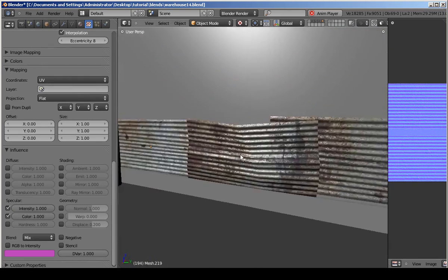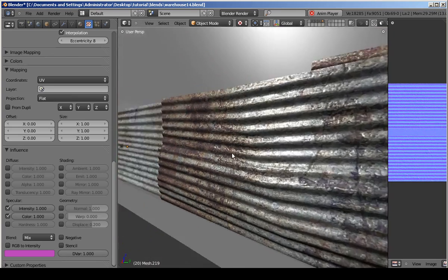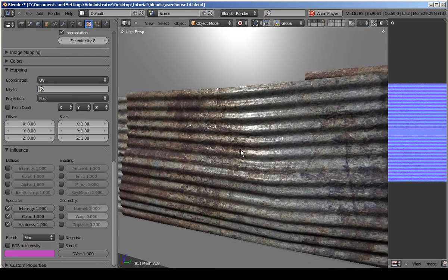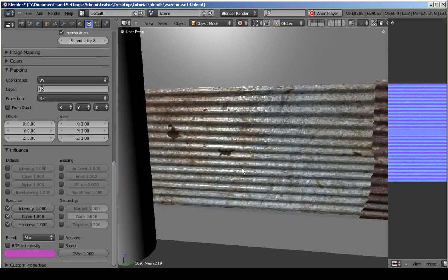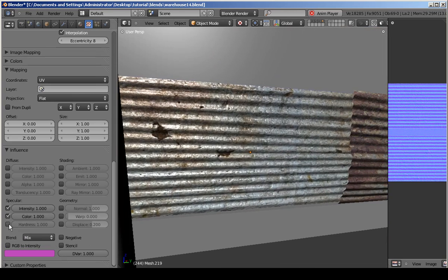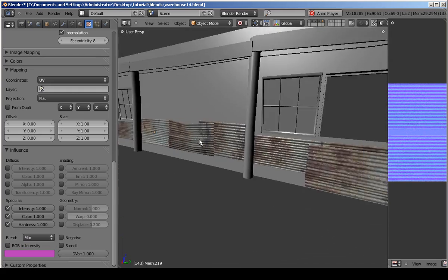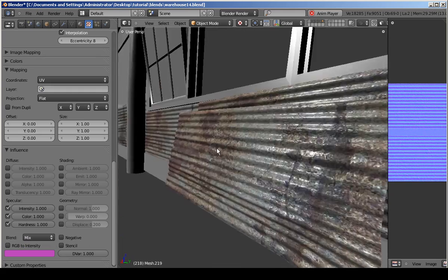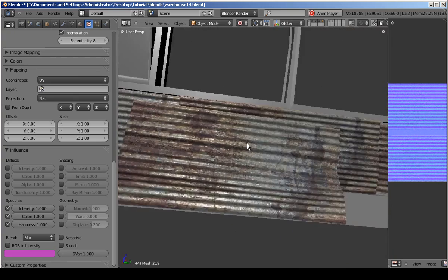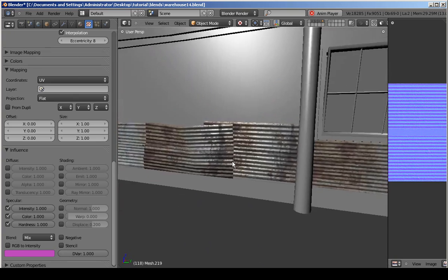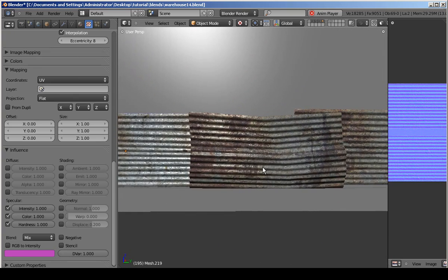I have them both enabled right now at value 1. And I just turned on hardness at value 1. I think I have specularity still turned on to about 0.5 in the material settings. So that's what's confusing me right now, because I'm wondering why there's a little bit extra shine when there shouldn't be.